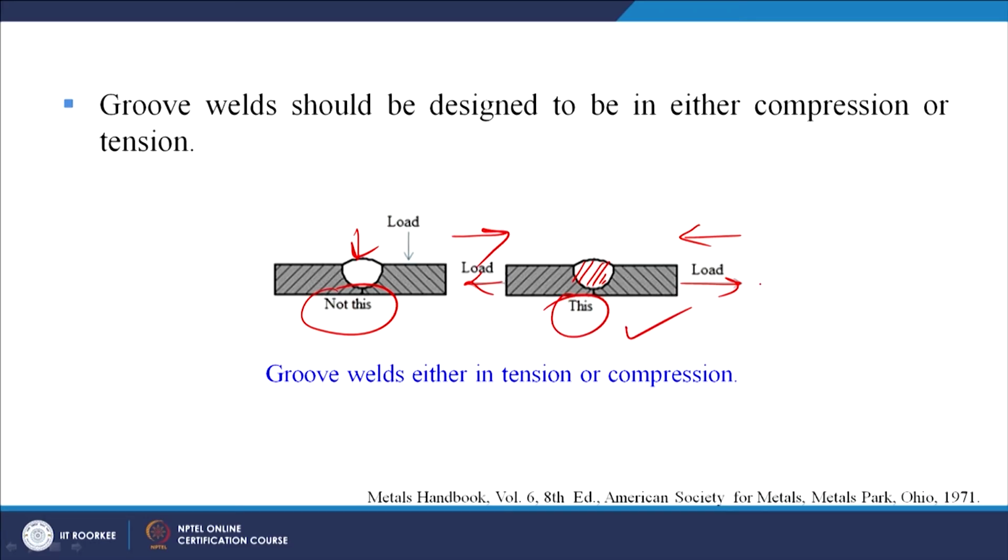So groove welds should be either in tension or compression. That is what we must ensure. And here, if it is supported from here, it is a kind of a bending problem. So we must ensure that groove welds are designed either in compression or in tension.